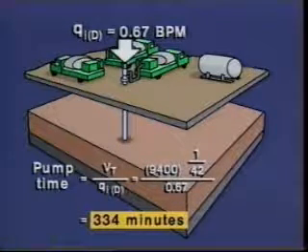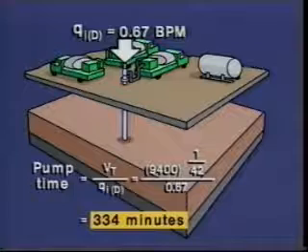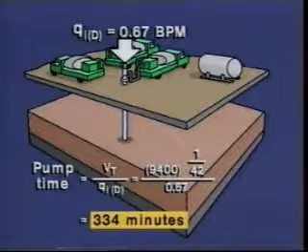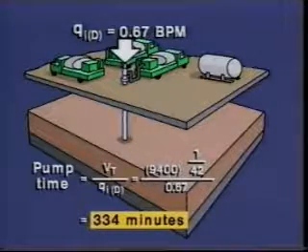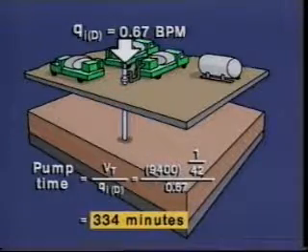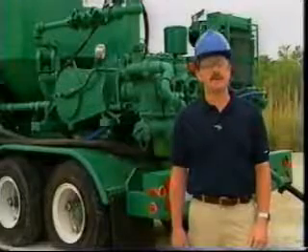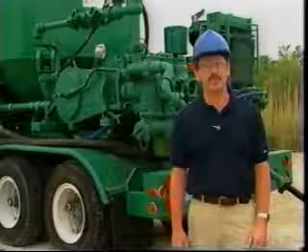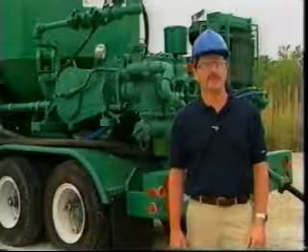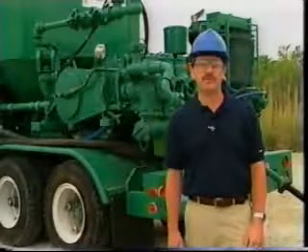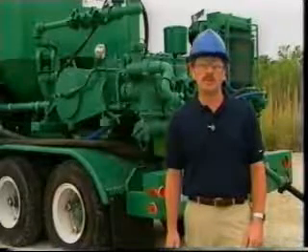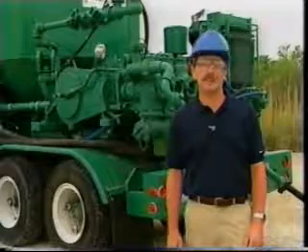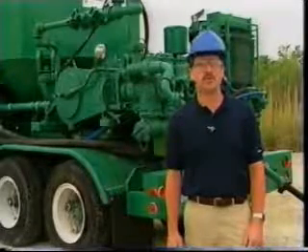pump the total treatment. The spent acid should not be left in the formation for extended periods of time because precipitates, emulsions, and sludge can form and have harmful effects. Based on the calculated injection rate of 0.67 barrels per minute, 2 hours and 30 minutes will be required to pump the HF acid. If the treatment injection rate is greater than expected, a minimum contact time of 2 hours will be needed to realize significant acid reaction and prevent the recovery of very strong acid.